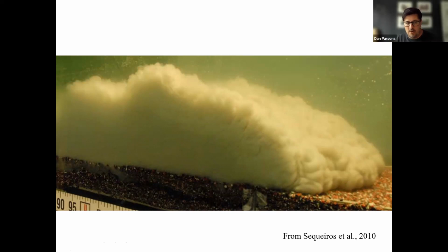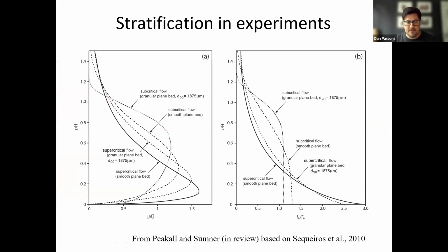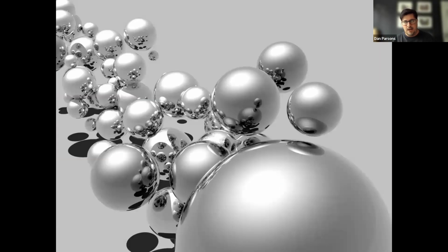So there are two ways to go, where we've taken some really valuable results in the flume, such as these here, with a whole host of scaling problems with them, and we take them out into the field or into a numerical approach to see if we can come past these things, because ultimately trying to scale sediment transport of these types of flows means we're beginning to run into problems with fall velocities of the particles, trying to get the turbulence levels correct for the types of flows that we have, because the turbulence doesn't scale properly either.